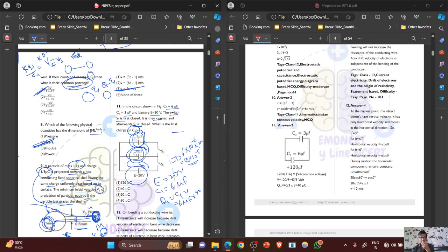As this has this charge, as you can see here it is also written. Now it is fully charged. Now it will charge the second capacitor up to the time when both get the same potential, meaning V is the same for them. So what will be the charge? We know Q equals CV, so V equals Q by C. Let's suppose a charge small q comes here, so here it leaves Q minus q. So your potential will be simply (Q minus q) by C1 equals small q by C2.